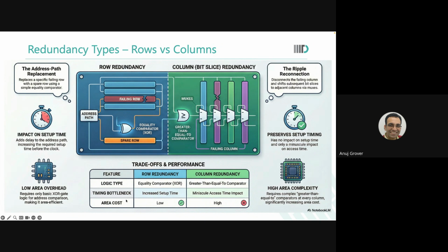At the time of power up, when your memory starts to receive the failing address again, this ripple shift has to happen again. Every time you power up. So there is a wait period before you can start to access the memory again. So this leads to a system constraint.